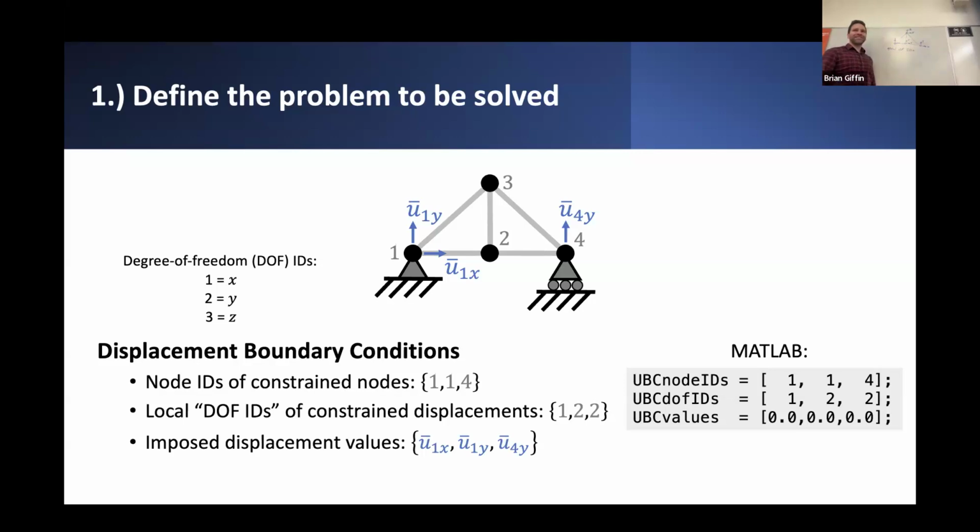can be determined from a formula. If I know which node ID I'm looking at, let's say node 2, let's denote this with node index I. And let's say I also happen to know that I want to constrain a particular local degree of freedom index, which I'll call local degree of freedom index 2, or the y component of this node.